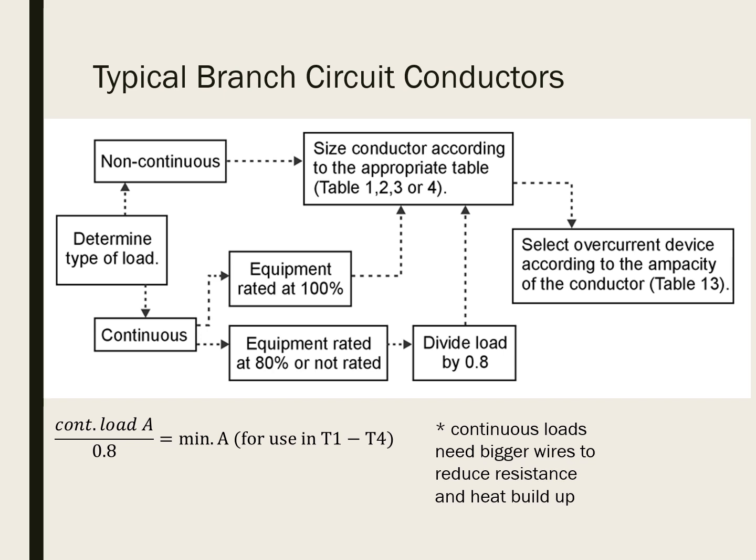Normally, most of the breakers that you're going to be working with are only rated at 80%. Therefore, we can only load it up to 80% of what its rated value is. So for a 15 amp circuit, we can only load it to 12 amps. A 20 amp circuit can only be loaded to 16 amps. A 30 amp circuit can only be loaded to 24 amps, and so on and so forth.